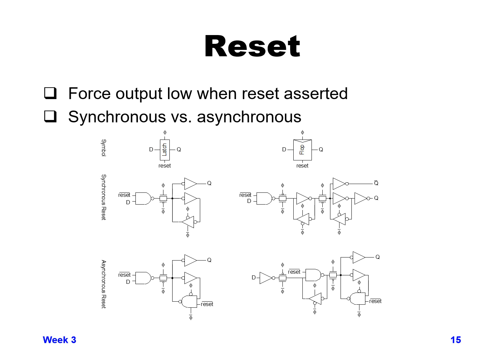For asynchronous reset, the way that you can do that in a latch, you do the same input NAND gate, but then in the tri-state feedback for the state element, instead of having just an inverting tri-state feedback, you have a NAND gate tri-state feedback that also has the reset bar.